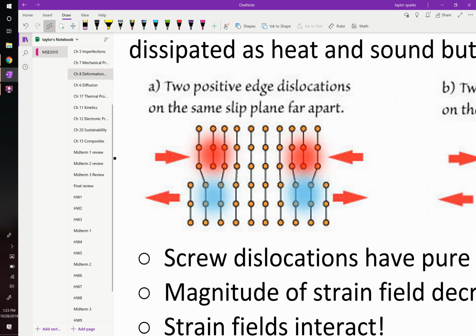But when you cram an extra half row of atoms in there, these things are closer than they wanted to be. Therefore, on top of this, where the extra half row is, that region of the lattice is under compressive stress. And basically, it's most intense right at the point of the dislocation, and it gets relieved the further away you go. Or in other words, inches away in the material, you don't see the strain of that thing. It's resolved. But in the near vicinity of it, you see that strain pretty acutely.